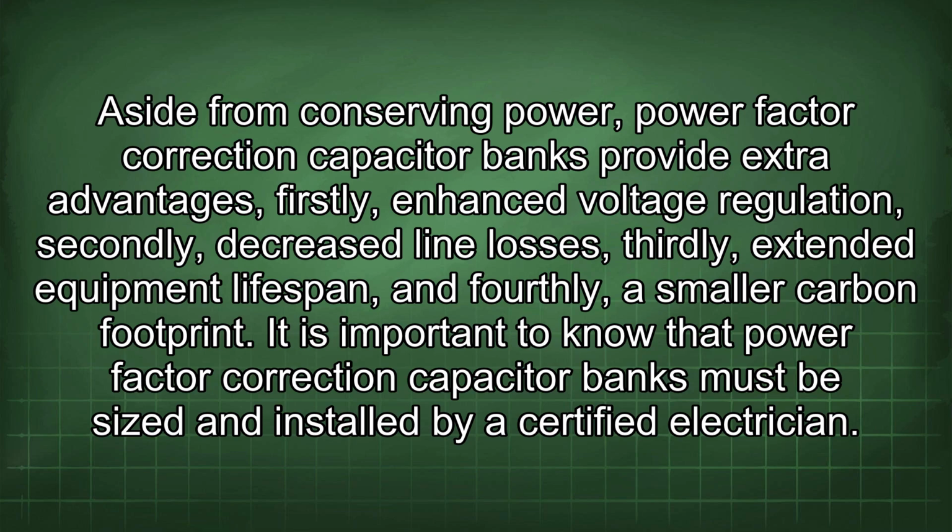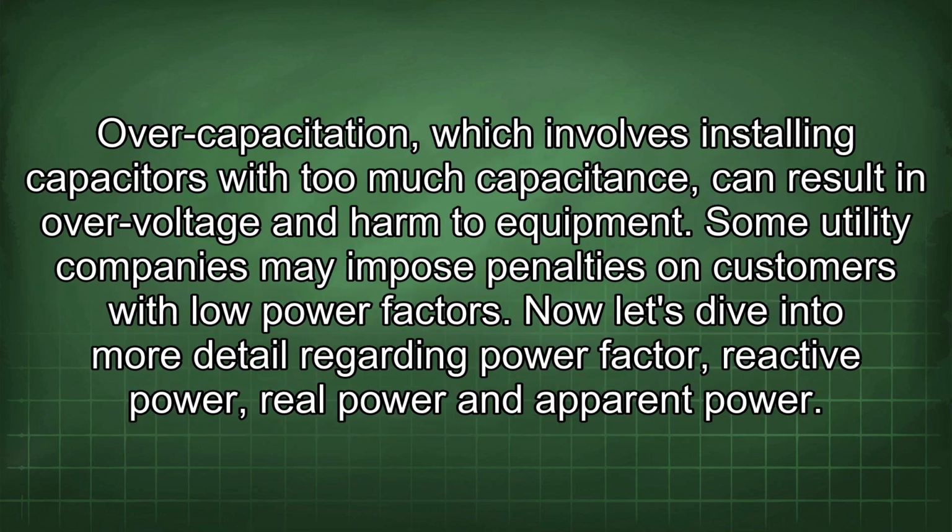It is important to know that power factor correction capacitor banks must be sized and installed by a certified electrician. Overcapacitation, which involves installing capacitors with too much capacitance, can result in overvoltage and harm to equipment. Some utility companies may impose penalties on customers with low power factors.